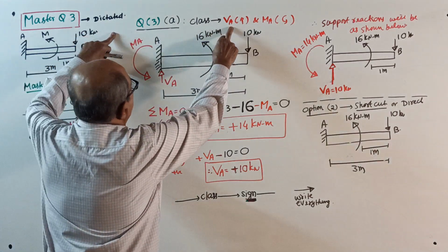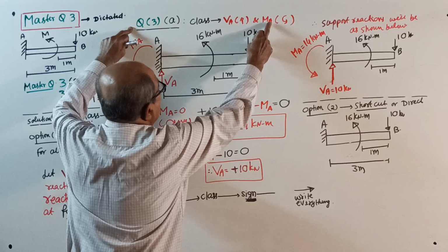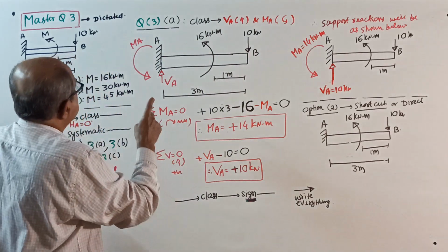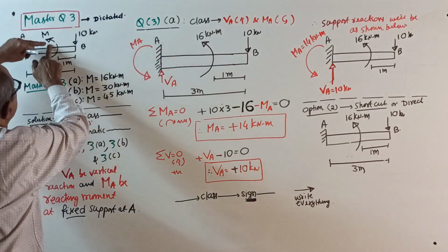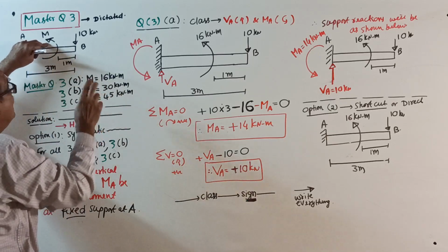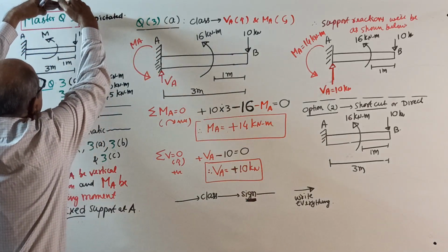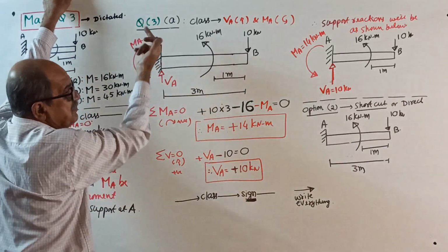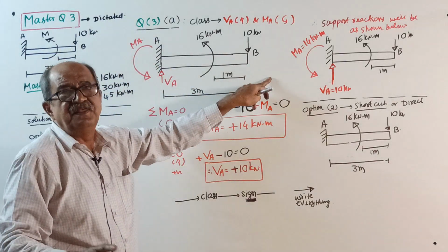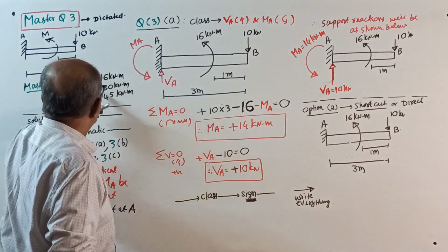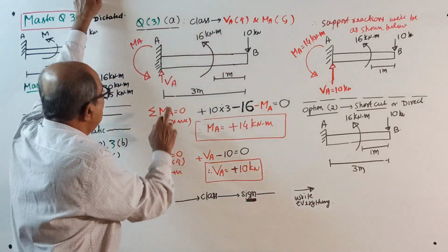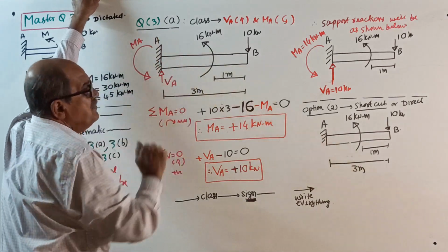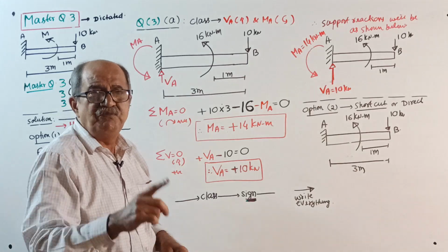Start. Now, first step, direction of reaction to be assumed. What all I tell, you have to write. First, vertical reaction. See, this is a couple. Remember, this is a couple. There is a vertically downward load, the action. So, reaction will be vertically up, guaranteed. Every class, I will not tell this now. For all 3 cases, VA will take upward. Okay, then reacting moment MA. See now, everything you write.